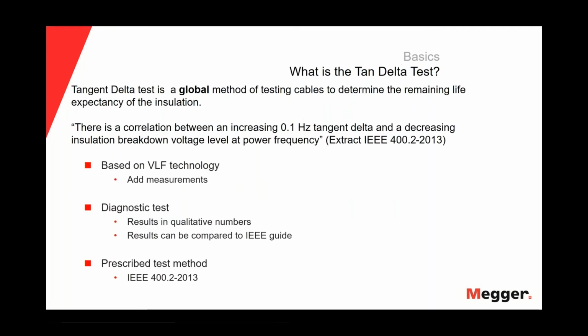So, what is the tan delta test? Okay, well, we can say that the tan delta or tangent delta test is a global method of testing cables to determine the remaining life expectancy of the insulation. We know that there is a correlation between an increase of 0.1 hertz tangent delta and a decrease in insulation breakdown voltage level at power frequencies.